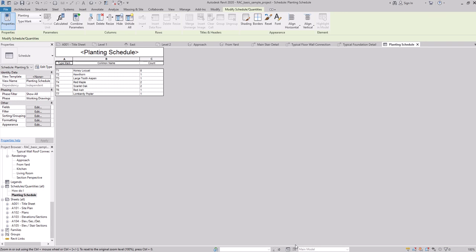We have parametric components in Revit, which are also known as families. So one of the strengths of component families is that they can be controlled by parameters, which allows for a great deal of flexibility. Parameters can control more than just sizes and distances. They can control materials, visibility status, and non-graphical information such as catalog numbers, voltage, and so on.